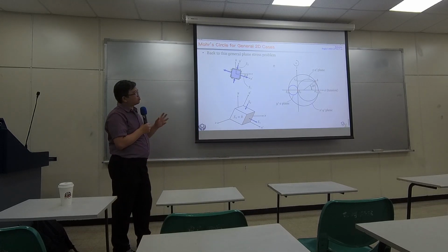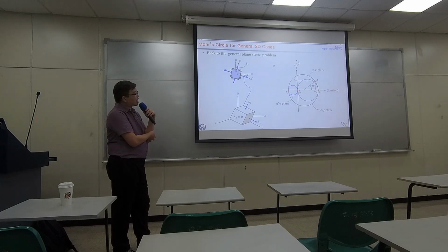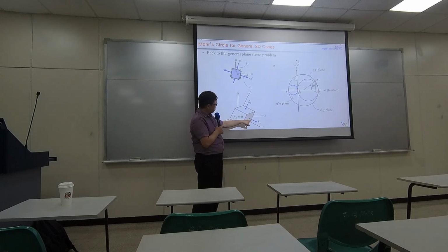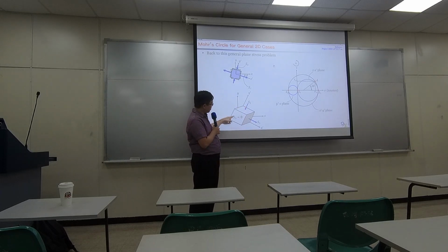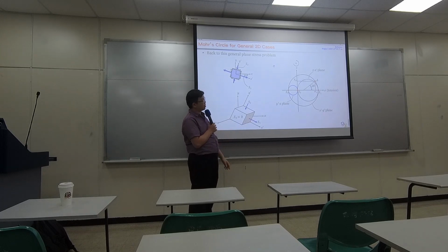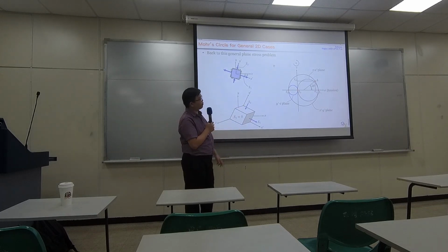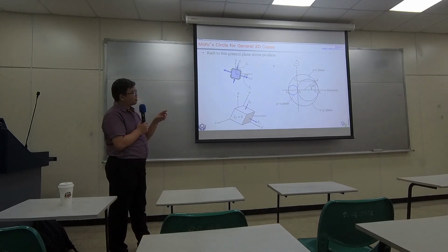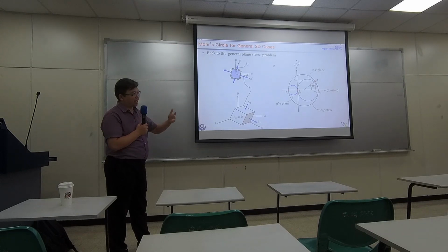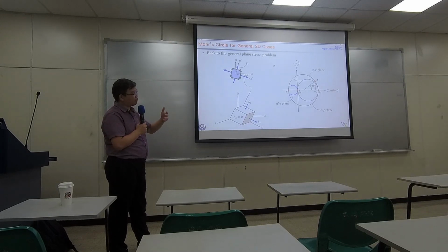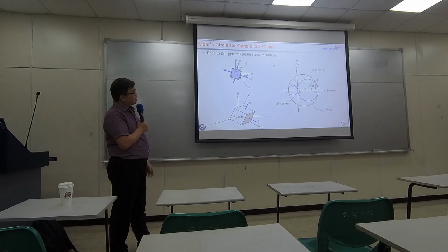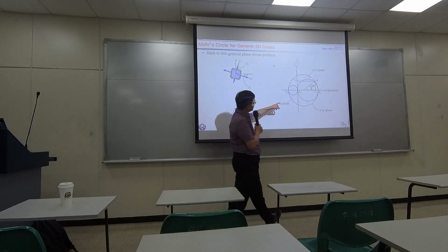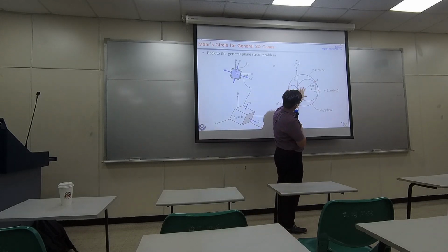In that case, you can study the Mohr circle between the first and second coordinates, the second and third coordinates, and the third and first coordinates. In fact, we have 3 Mohr circles. Each Mohr circle represents a working plane, either 1-2, 2-3, or 3-1, right? And it happens that the stress along the third direction is 0, so you have circles like these.